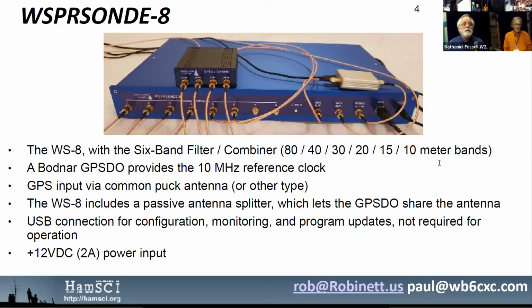With WSPR, the data that's encoded in the WSPR frame is call sign, a power level, just a numbered, basically dBm transmit power, and your grid square, your HAM's grid square, which is your location. You take latitude and longitude and some simple conversion, you get grid square. So we do all that.